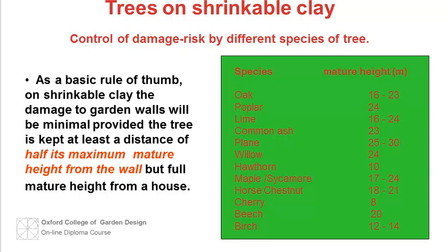Garden designers must be aware of these potentially very expensive effects on both existing and proposed houses and on hard landscape construction. You should therefore check whether the site is in an area of shrinkable clay. This is prevalent in the southeast of England. Consider existing major trees or trees which may have been felled and the future effect they may have on any walls, drives that you are now proposing.